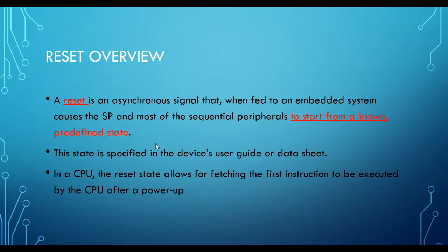Now we go into something that's more clear-cut, a reset. Okay, so what is reset? Watchdog, for example, is a type of reset. Reset is an asynchronous signal that, when fed to an embedded system, causes the CPU and the most sequential peripherals to start from a predefined state.